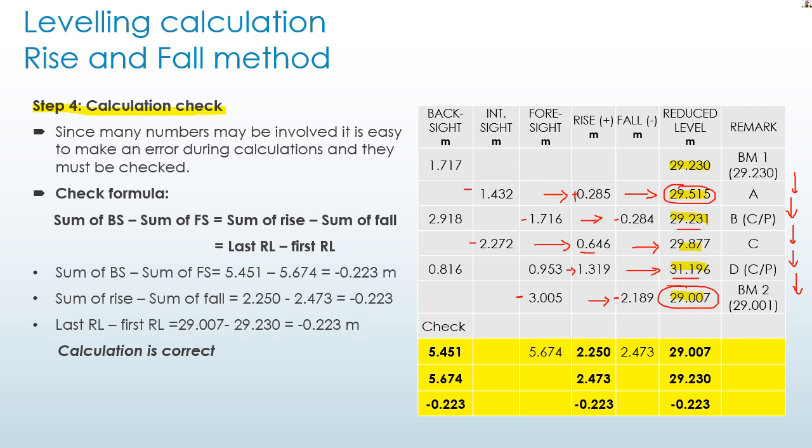Normally it's not going to be equal to the known elevation of that benchmark, because we always have some errors, due to instrument errors, natural errors, or personal errors. A few millimeters is acceptable. In this case, we're going to explain it in the next slide.